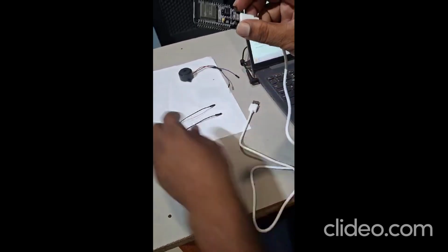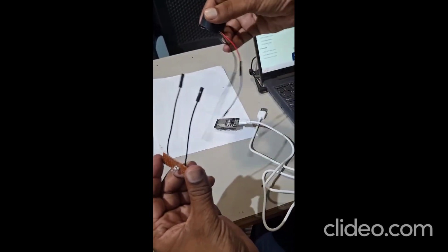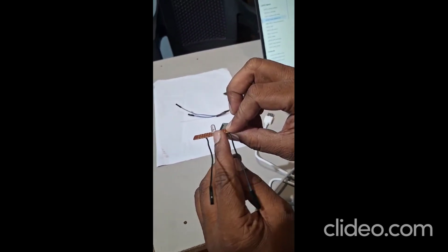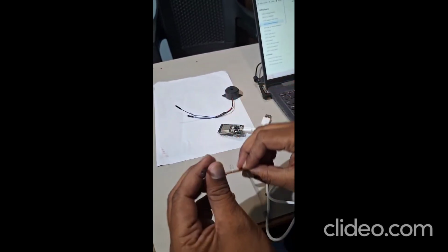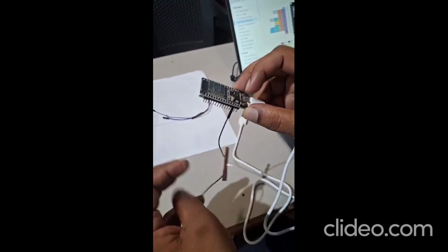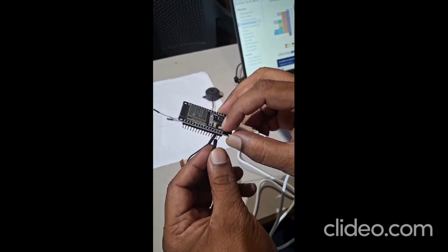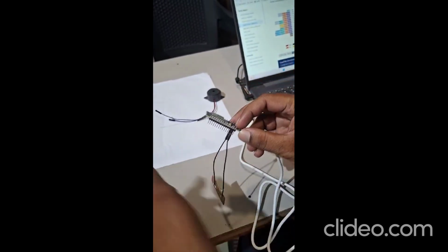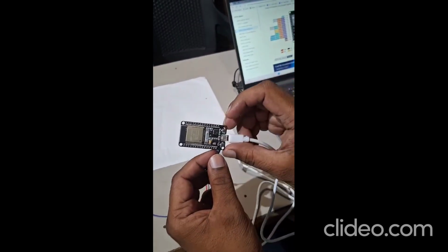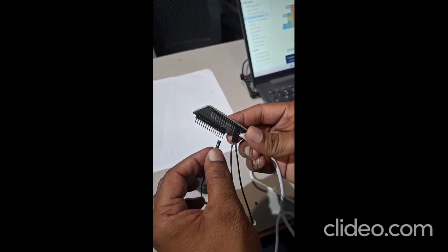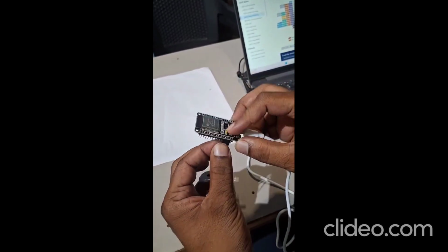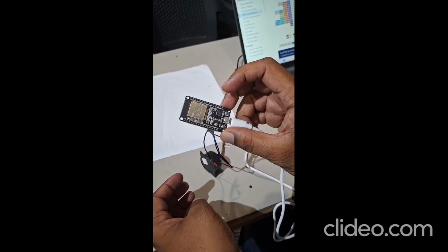So 2 actuators we are going to connect. This is one LED and this is one buzzer. For the LED positive, you identify the positive. I told in some videos how to identify them. Just identify the positive and connect it to the 13th pin, because in the program I mentioned the 13th pin. Wherever you find ground, the other pin of the LED is connected to the ground. Next is the buzzer pin. Some other place will also have some grounds, so you connect to the ground pin here. Then the buzzer pin is connected to the 12th pin, D12, as I mentioned D12 in the program.